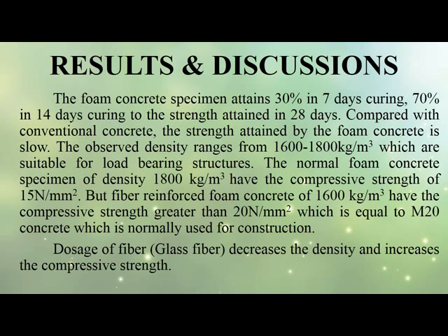Results and discussion. The foam concrete specimen attains 30% in 7 days curing and 70% in 14 days curing of the strength attained in 28 days. Compared with conventional concrete, the strength attained by the foam concrete is low. The observed density ranges from 1600 to 1800 kg per cubic meter, which is suitable for load-bearing structures.